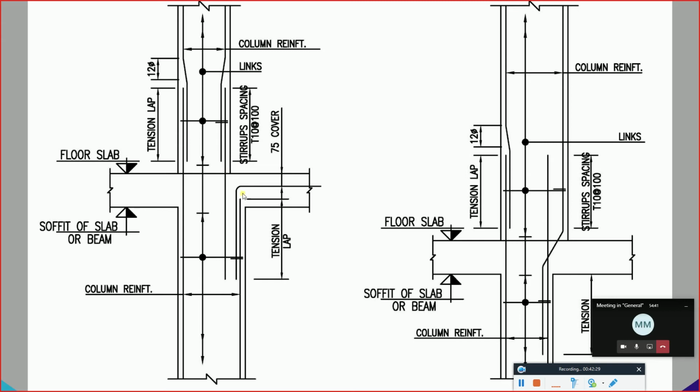Now the other side, you can see that the ends are not the same. This is bigger, this is smaller. So what we need to do, first we need to supply the reinforcement for the end. Since it's a floor here, we need to do the lapping, the connection, as it is a roof column, because this is stopping here now. And then we need to initiate a new reinforcement to start in this particular end of the column.